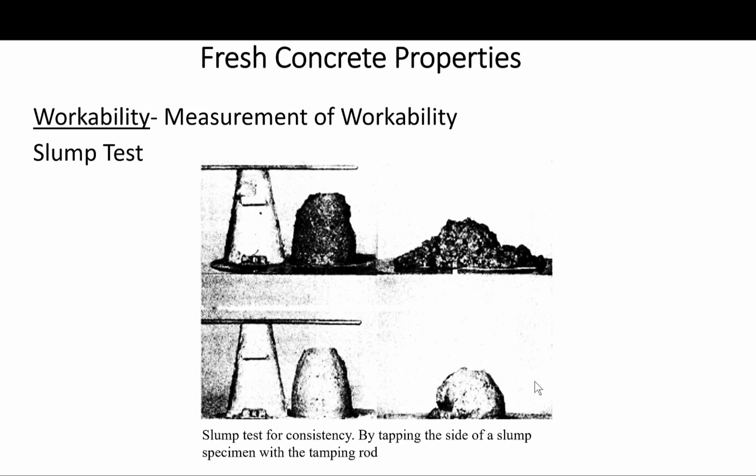In addition, the slump test cannot differentiate between low workability concretes, which may all give no slump, or concretes with slumps less than 25 mm. Concretes with slumps less than 25 mm should be tested by another procedure, preferably one involving vibration, since vibration will be needed to consolidate such stiff concrete.